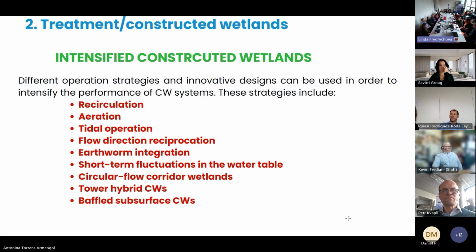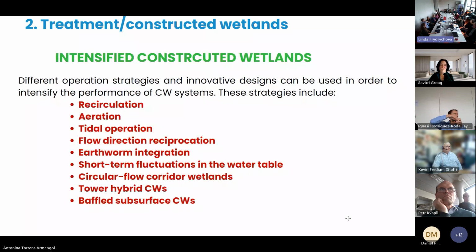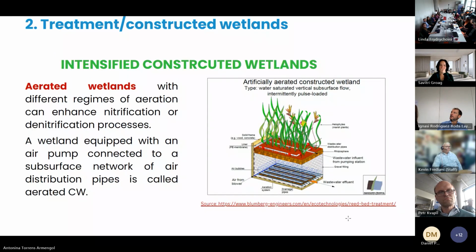We have a lot of systems. It's also to give aeration, no? Yes. The worms create holes, and so aeration is much better. And these are the aerated wetlands. Yeah, here. That is just a wetland equipped with an air pump, using a very, very small amount of energy, and it works quite a bit better for removal of some pathogens and some BOD.